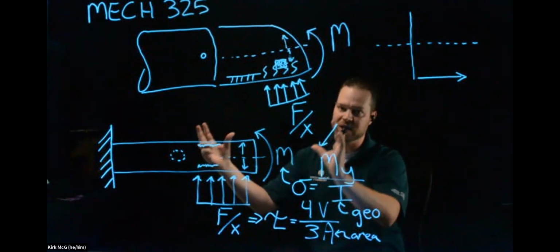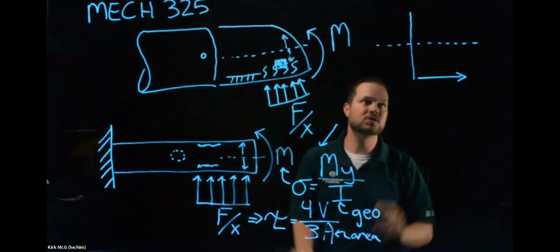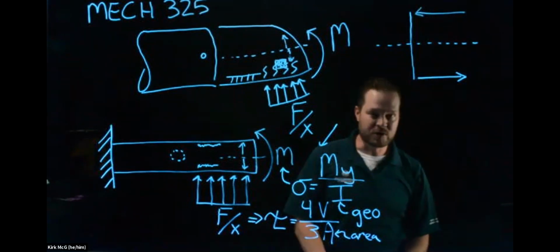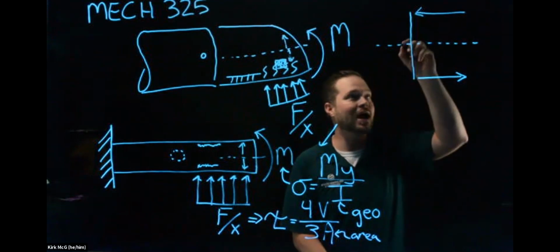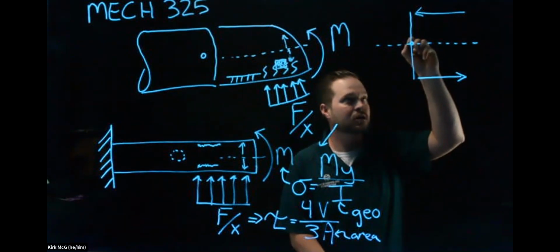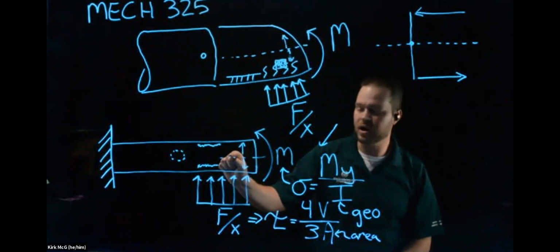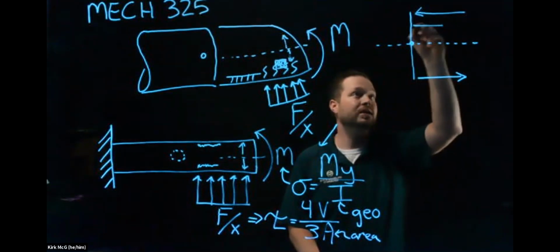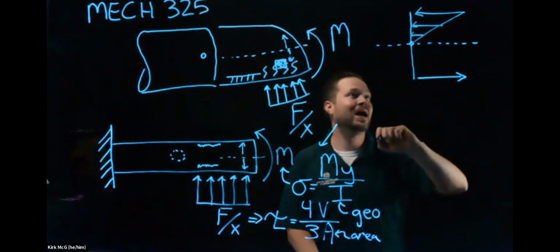As we imagine this beam is being compressed or bent up, we're doing this. Well, these fibers are now in compression, okay? And what we know and what we'll learn in this class, we won't go into the details of the math behind it, but basically at this neutral axis here, there is no stress in bending. Meaning if I was to put a hole there, it would not be under stress because the stress profile kind of looks like this. It decreases towards the neutral axis.